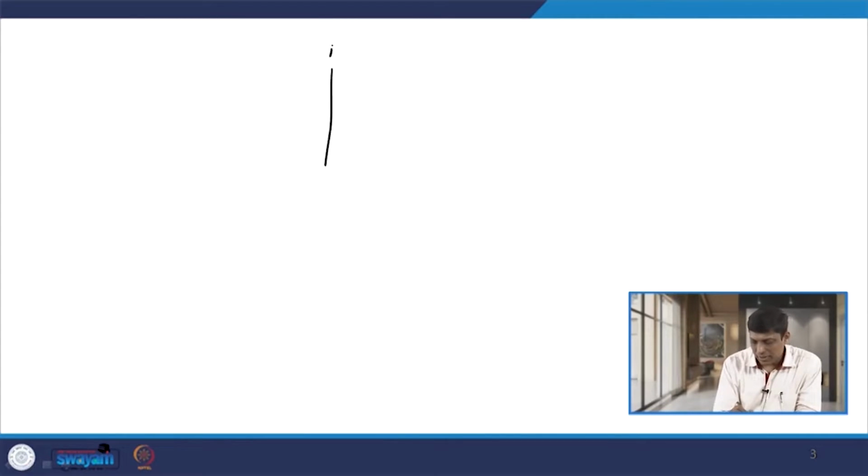As I have already discussed in the last class, the distance relay measures the impedance from the relaying point to the fault point, and this impedance is the positive sequence impedance. On the other hand, if we use ground distance relays, then it is based on zero sequence impedance. Whenever we put a distance relay in the circuit, let us say a bus A, with a line connected between A and B, we put one distance relay R here, which is also fed by the line PT.